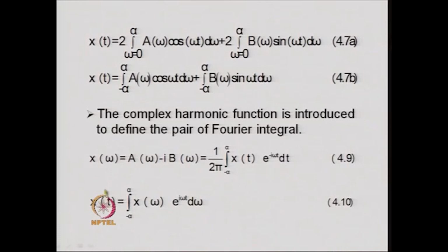The second part, that is, if we wish to find x(t) given X(omega), the frequency contents of the ground motion, then we use the IFFT, that is, the inverse Fourier transform.